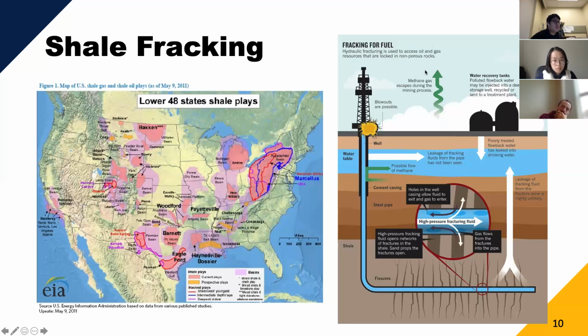This procedure does horizontal drilling, where you go across a shale area that has lots of fissures. As you pump water through these areas, it displaces all of the gas, and a lot of it dissolves into the water, and you can extract it back up. This process can be seen here.